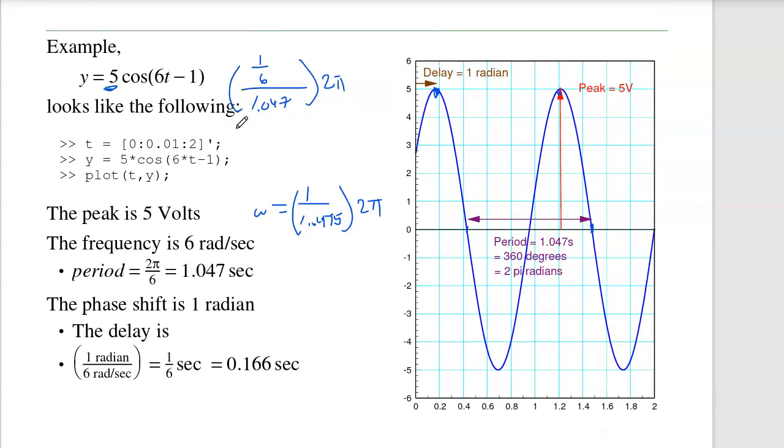So that's kind of one thing to note. There's two forms. There's rectangular form and polar form. In the lab, when you'll use an oscilloscope or look at a graph, polar form is much more natural. So personally what I do is if I'm in the lab, I use polar form. That gives me the amplitude and the delay. In calculations, I like rectangular form, sines and cosines. But they're interchangeable.